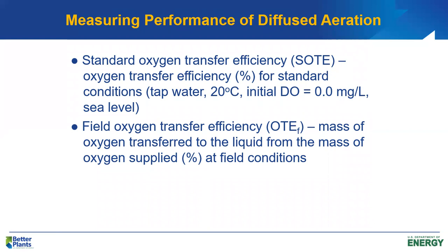That's how we measure our aeration equipment at standard conditions. At standard conditions, the oxygen transfer efficiency for a porous diffused aeration system will typically be 10 to 15%. For a non-porous diffused air system, the standard oxygen transfer efficiency would be about 2/3 of what it is for a porous diffused air system.